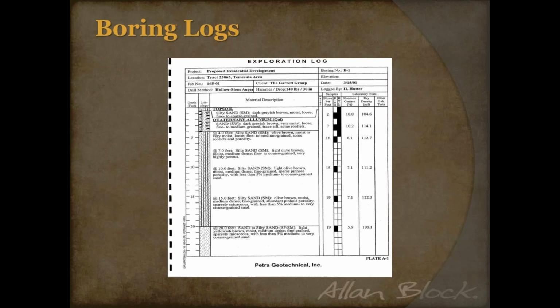But I often stop here, especially when I'm working with our producing partners and our contractors out there. A lot of times, even engineers want some assistance from Allen Block Corporate, which we're happy to do. We're happy to give some technical assistance, do some preliminary design work, go through it. And it often makes me laugh when we get 50 pages of boring logs in a geotechnical report, because you see this is great. It might give you a broad brush stroke or a broad brush view of what the soils might look like, but it doesn't really give you the shear test, the friction angle,